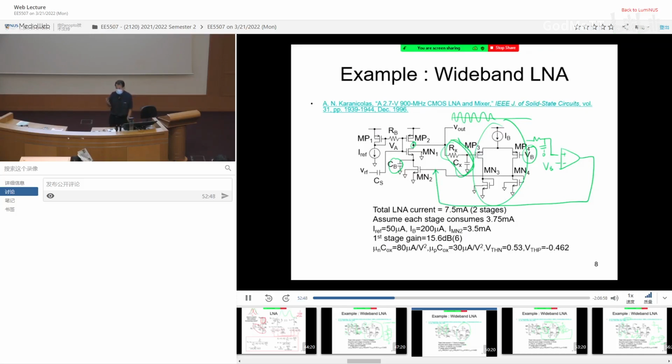So for negative feedback, eventually, due to the virtual short, the DC of this guy is going to be exactly equal to VB. Am I right? So this technique is using the negative feedback to establish what is the final DC that you will allow for this RF circuit.